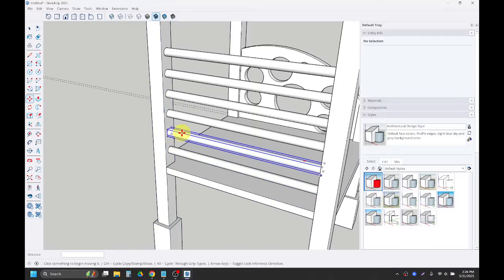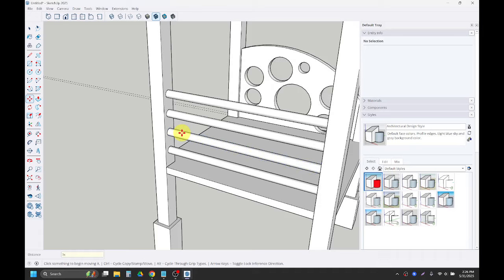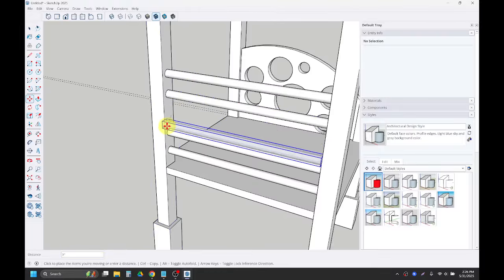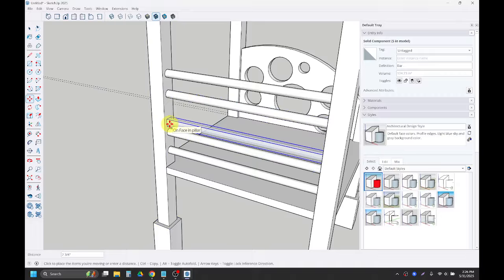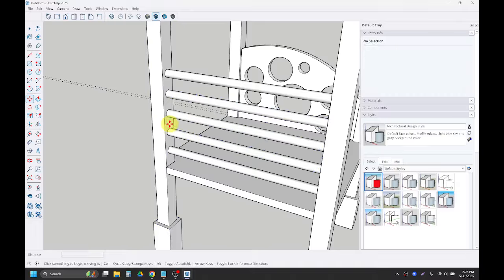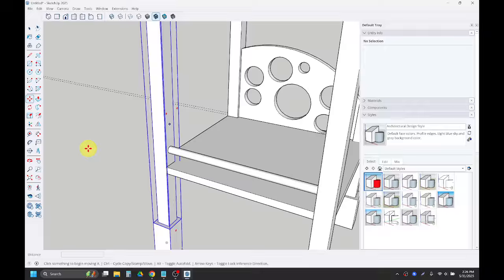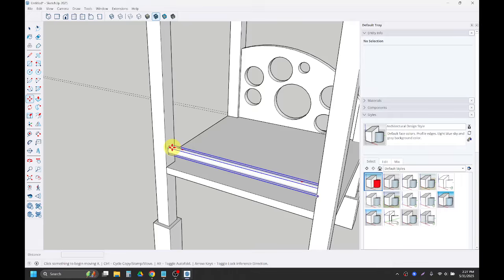Now, sometimes if you've clicked somewhere else accidentally while making your copies, you can't make these changes to it. So while I'm still in this copy tool, I could change it to 3x, enter, and then I've made 3 copies of it. Or I could do 4x, enter. But once I click somewhere else, I'm out of that copy tool. So if your array doesn't work, you can always just do Control Z to undo, and then start the Move tool again with keyboard shortcut M, and try again.